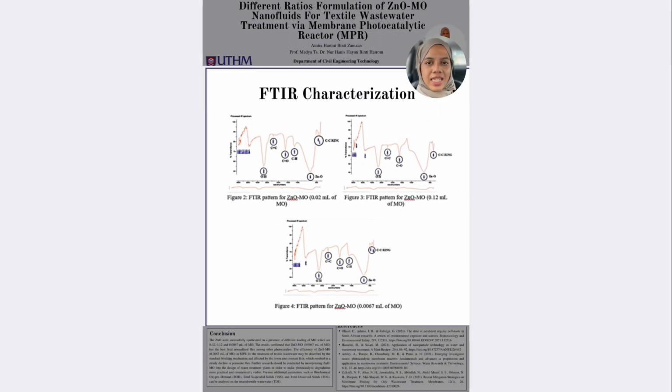For the results and discussion, for the characterization of ZnO-MO nanofluids, the obtained FTIR data showed the functional groups of hydroxy group, carboxylic group, carbonyl group, ZnO, CH stretching and CC ring. All ZnO-MO samples exhibit a nearly identical FTIR pattern with slightly varied values.